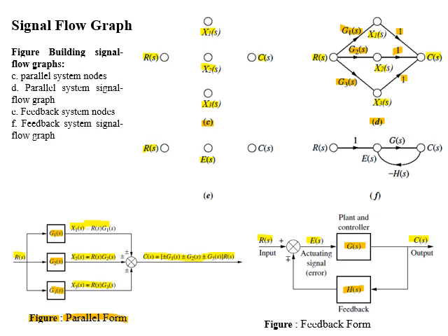In this we have the input signal, error signal and output signal. So for these 3 signals, we will draw 3 nodes. Now the input node and error node are connected with unit gain. The error node and output node are connected with transfer function G(S), so there will be a branch with a gain of G(S).